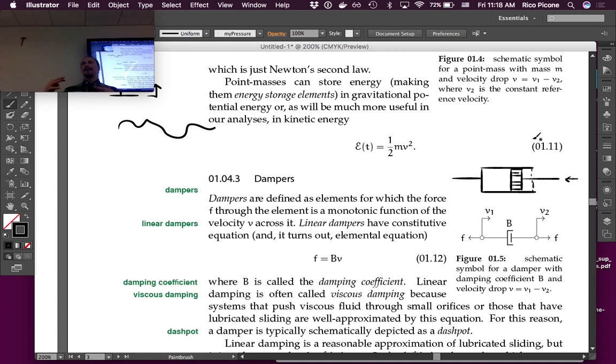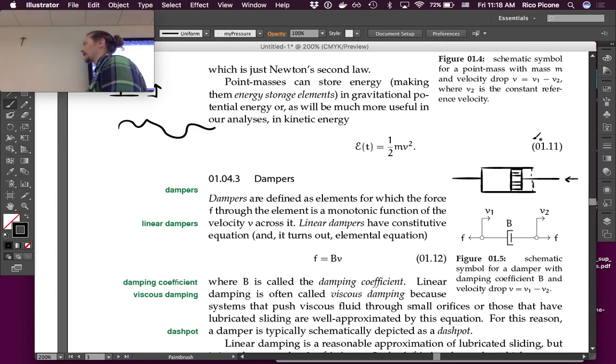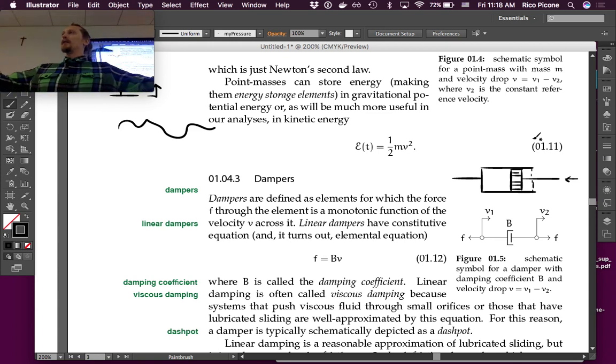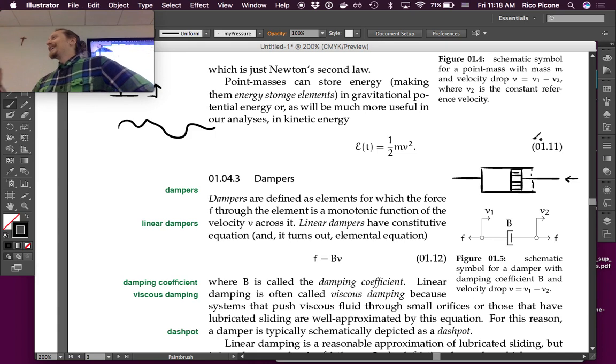They're not tiny holes, but they're small enough holes so that fluid can go through, but they can't all rush through at once, right? So when you do this, it turns out that the force you have to apply to move that piston is proportional to the velocity that you're pushing it through. So the faster you go, the more it resists, okay?